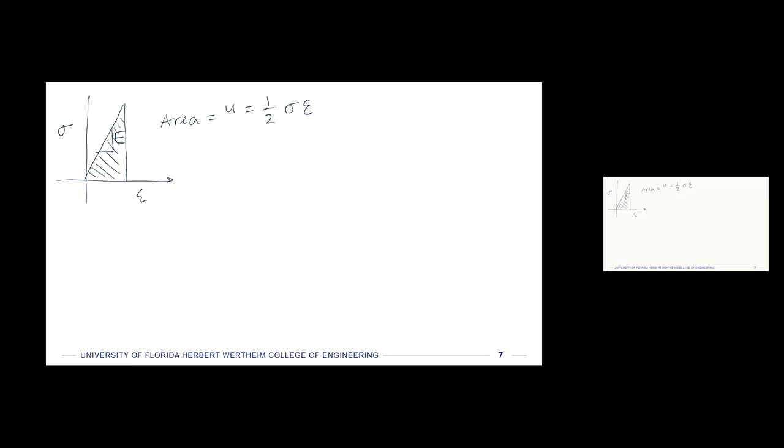When we talk about the strain energies moving forward, they're all going to be per unit volume, and that's going to help the units to work out, because we're always working with some kind of a volume that we're applying all these stresses to. So this is energy per unit volume. Energy is usually Newton meters, volume is meters cubed, so that comes out to be newtons per meter squared.